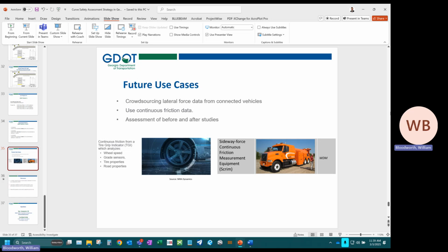And that's really the reason I want to switch to the lightweight aggregate, because it binds to the aggregate. There's no epoxy involved. If you take a look at the high friction surface treatment, I'm going to ask for that back afterwards, you can see the epoxy on it as well, and it looks like glass when it's hardened.